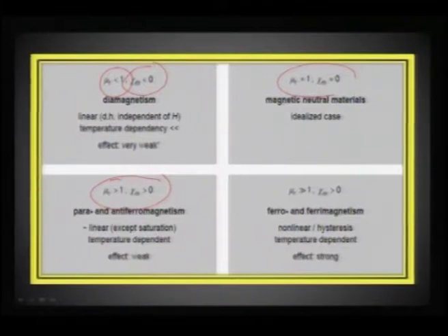In the case of ferromagnetic and ferrimagnetic materials, the permeability is far greater than 1 and the susceptibility is definitely greater than 0. What makes them candidly different is the hysteresis that emerges in ferro or ferrimagnetic materials, which is absent in paramagnetic materials. Therefore, there is a clear divide between these two, and it is easy to understand how a ferromagnetic material would respond against an antiferromagnetic material.